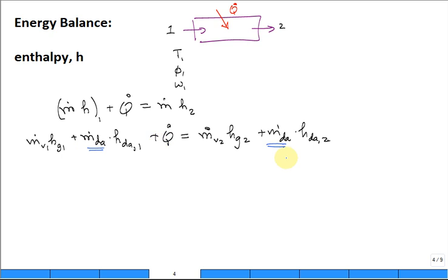But if you had a source of water, m dot liquid, how would you add that into the energy balance equation? Well, wouldn't it be another in over here? We'd have the mass flow rate of the liquid coming in plus that enthalpy of the liquid coming in. That would be saturated. It's coming in a liquid state, saturated liquid at whatever temperature it's coming in. True? Wouldn't that be how you adjust? And so you'd have to bring that down also to this equation right here.